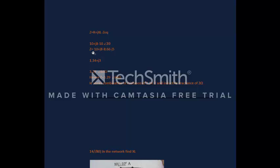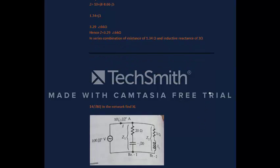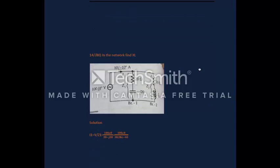So Z is equal to 10 plus 8j minus 8.66 minus j5, which turns out to be 1.34 plus j3. Therefore, we can write it as 3.29∠66° ohm. Hence, the unknown impedance is equal to 3.29∠66°. Therefore, a series combination of resistance of 1.34 ohm and resulting inductive reactance of 3 ohms.